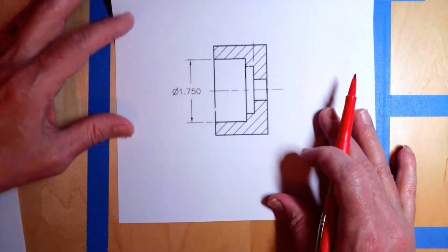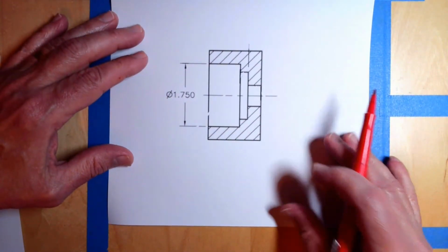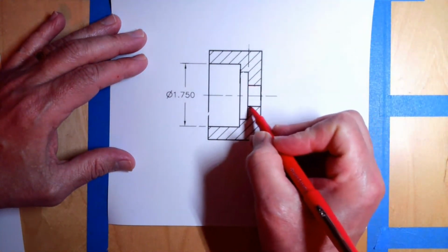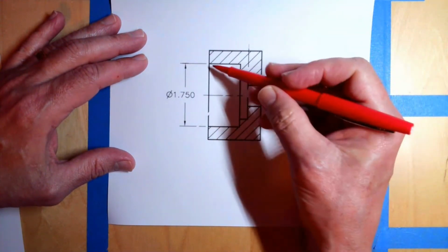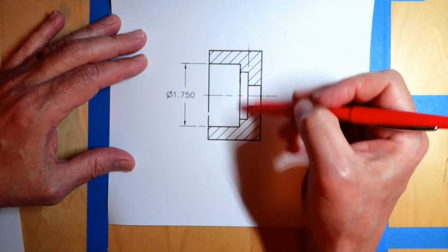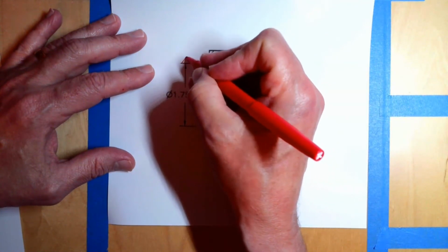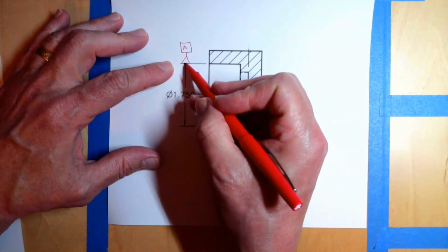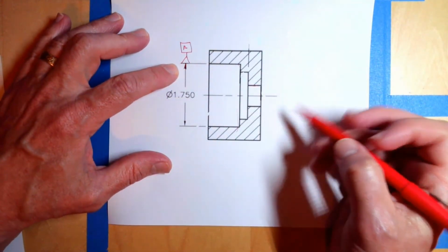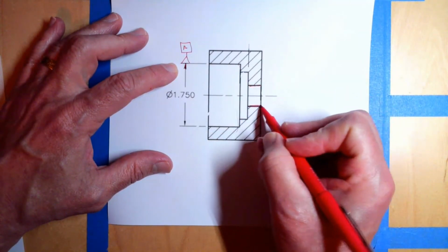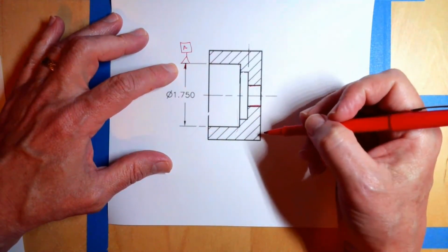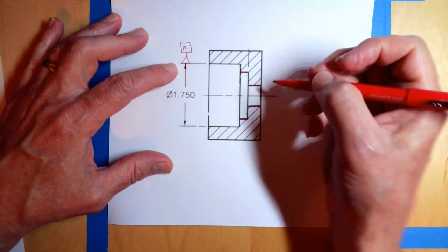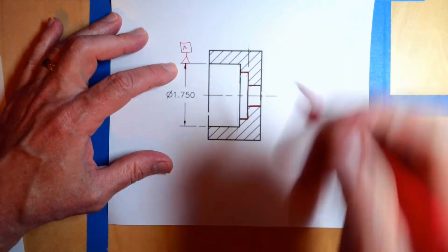Let's look at this other one down here. Now, on this one, we want to control the inside, this hole, as it's being held and rotating in this part. So this is going to be my datum feature of size A, and again, it's associated with the arrow here. But what I want to control is this hole. That's a hole, I want to control this hole. But I also want to control this surface here. So can we control that surface?